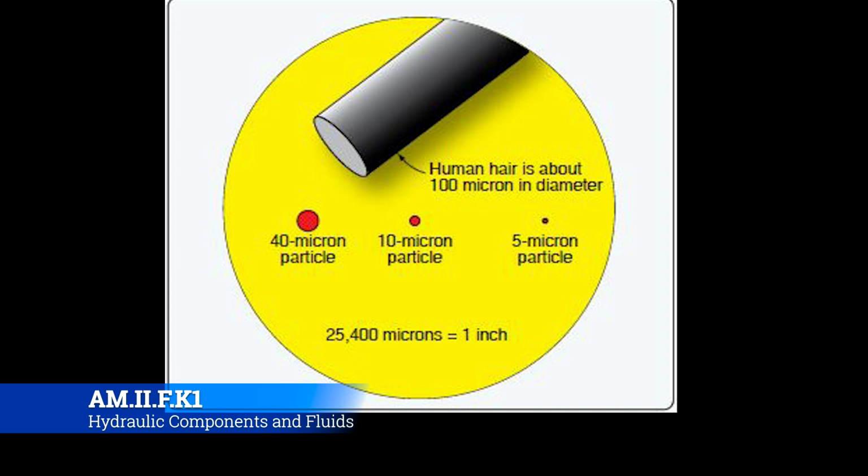Okay, so the next ubiquitous component that you're going to find in all hydraulic systems of any type is going to be some sort of filtration. Now, typically in hydraulic systems, you have micron filters. All right, so a typical micron filter assembly is employed, and the reason being is that little shards of debris inside of a hydraulic system can cause serious problems. As an industry, aviation has set a very high standard for filtration of its hydraulic fluid, and honestly, many of the other types of fluids out there.